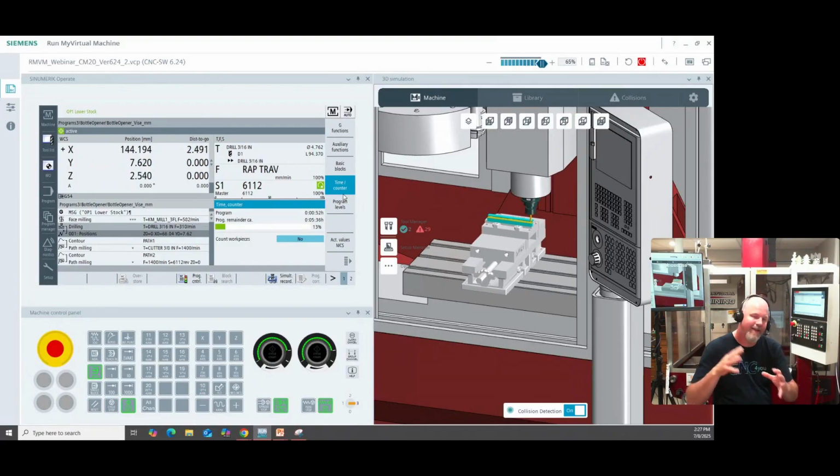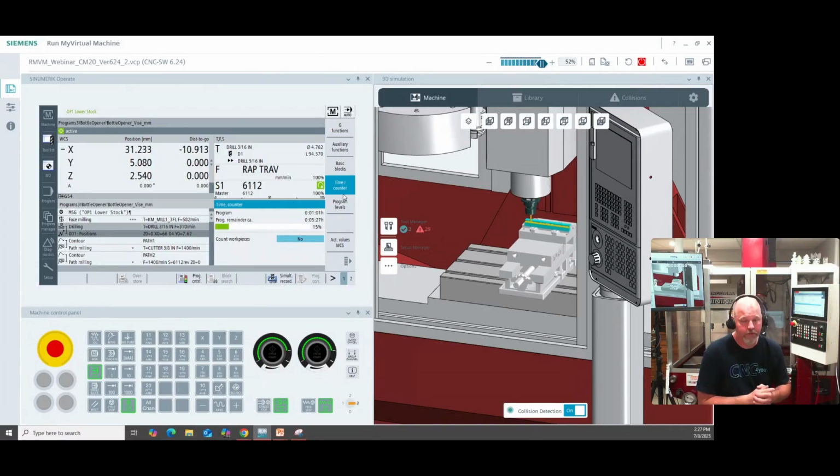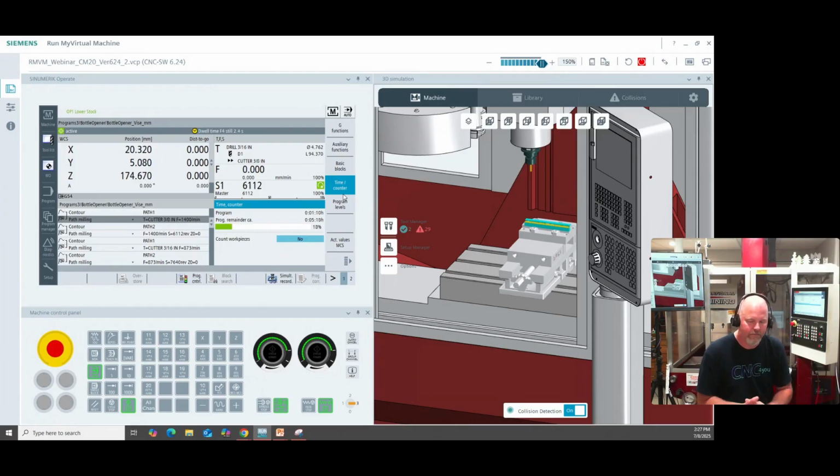So I'm not going to know exactly how much time it takes to tool change chip to chip. So even if I wanted to add in maybe 5 seconds, 10 seconds max per tool change on top of that time, that'd be about the only thing. On a servo driven tool changer, for sure, I would get basically a one-to-one because it now knows how long it takes to spin the carousel. That's about the biggest loss of time.